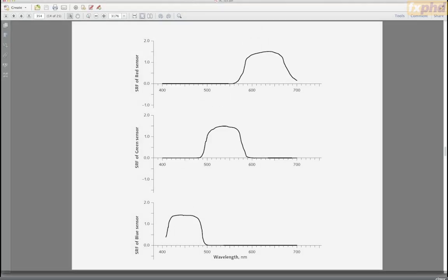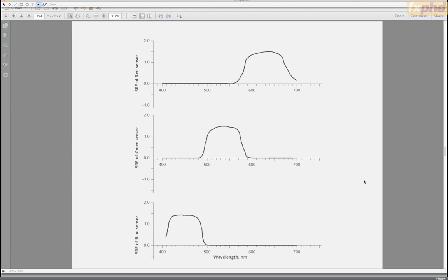So you start in the camera with curves that look something like this. Now, this set of curves, I can reveal to you in secret, is from an old Sony CCD camera. It's from an HDC F500, a really old one, almost 15 years old. And that camera used a beam splitter assembly. I showed you that whole beam splitter business of splitting out the red, the green, and the blue into 3 separate sensors. And there you can carefully manufacture the curves by making suitable filters.